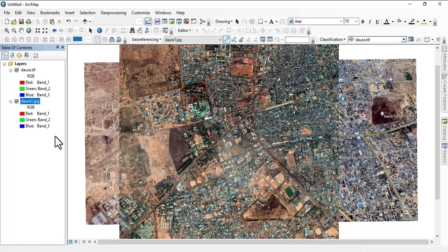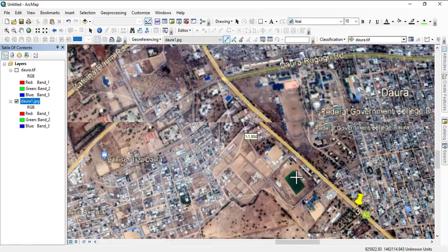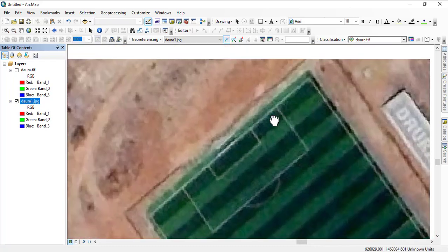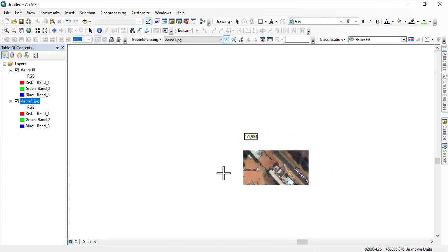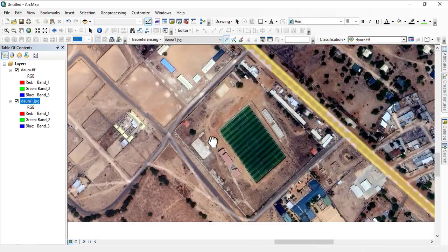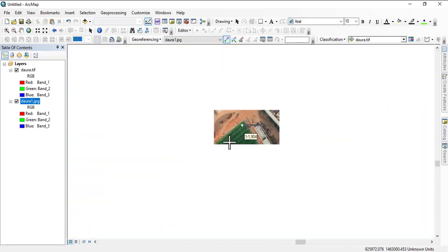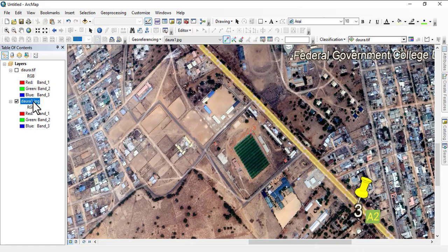Now you see that it's already come on where we are already georeferencing. So I'm going to now remove this, and then I'll pick this side of the image and bring this one back. Then locate the side here and click. And then finally I'm going to remove this and then get the last point.